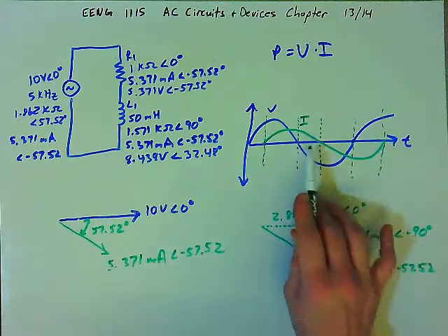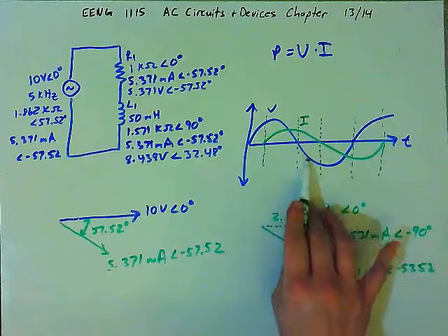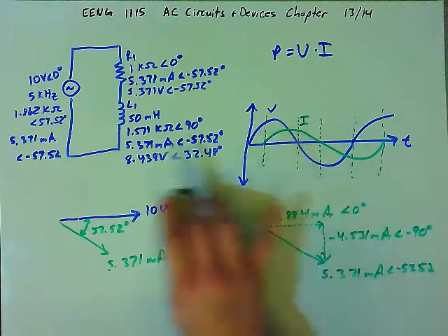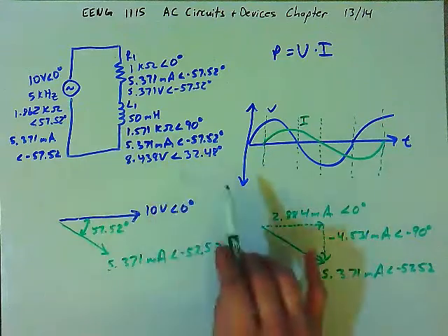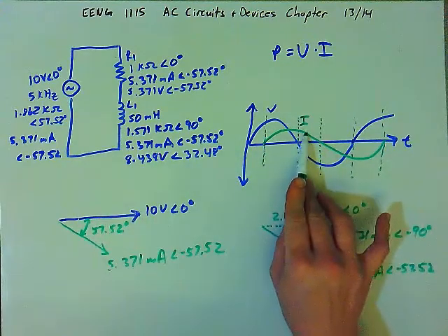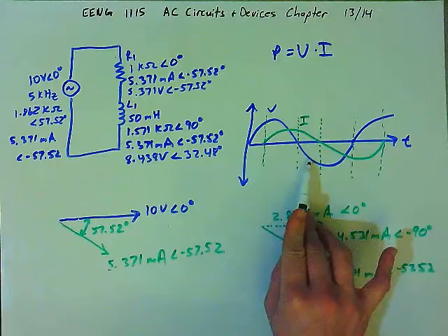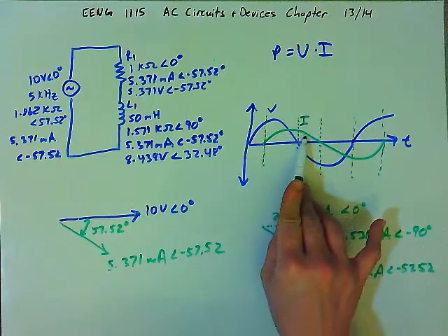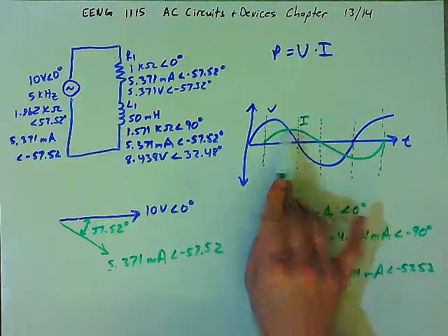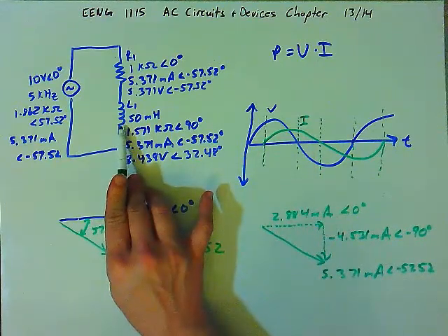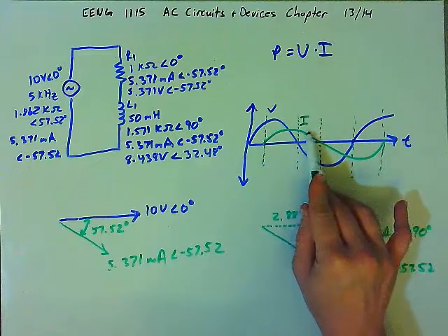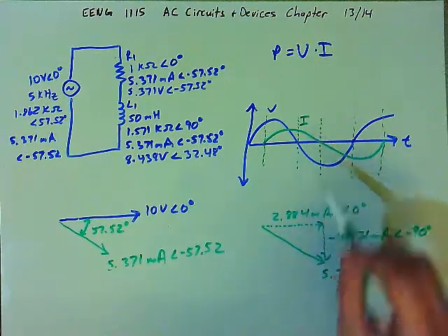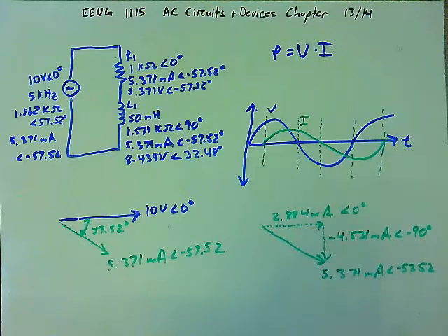And so what's happening here is the voltage is negative, but the current is still positive. That's because the magnetic field around the inductor is collapsing, and it's keeping the current flowing in the original direction even though the voltage has reversed polarity. And so here the current being supplied to the circuit is the energy being given up by the collapsing magnetic field. That was energy that was previously stored. So we consider that the imaginary component of the power.